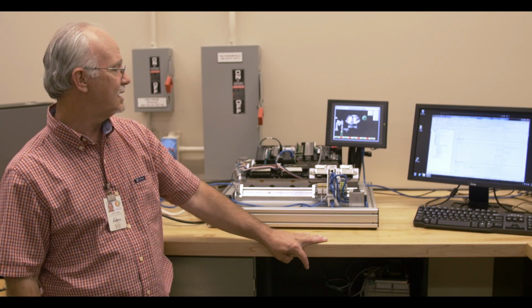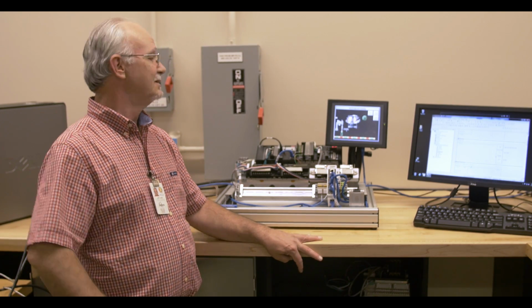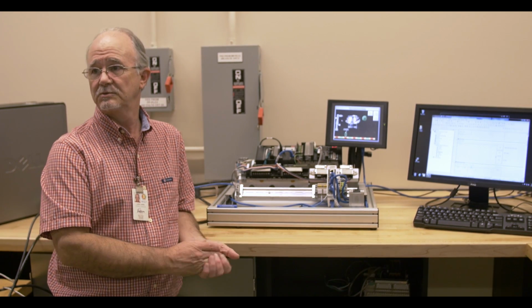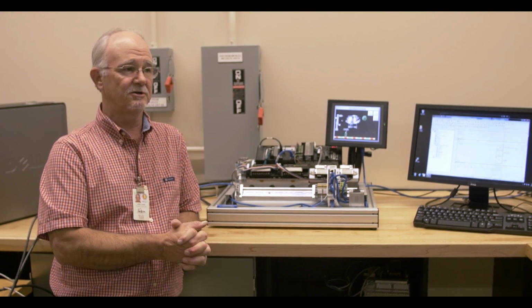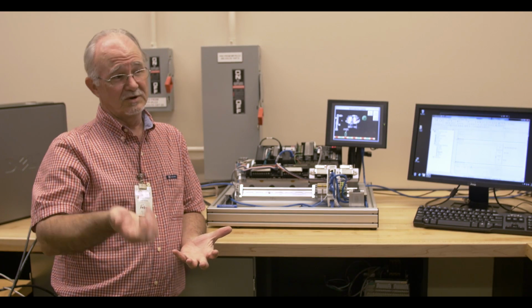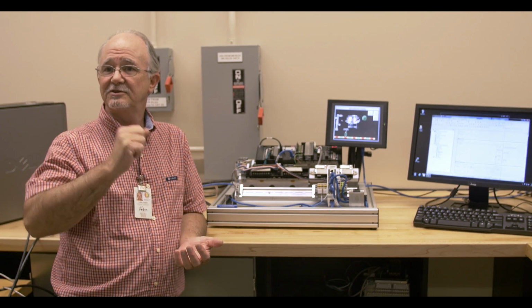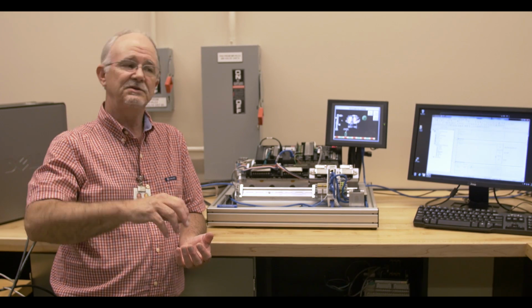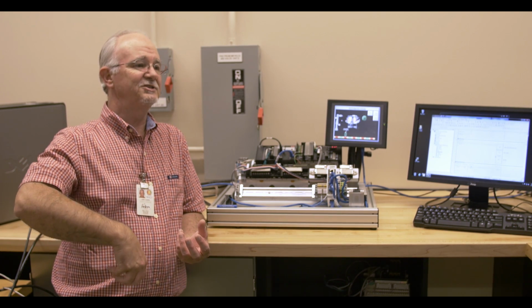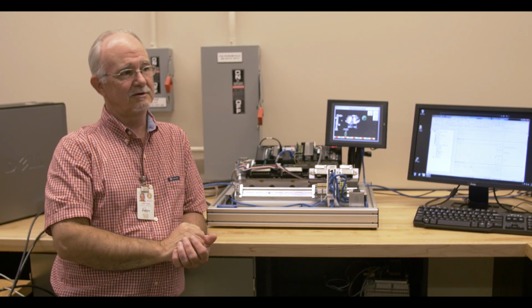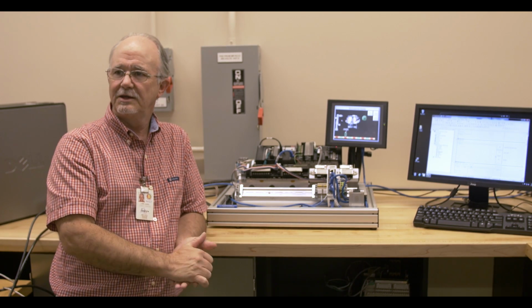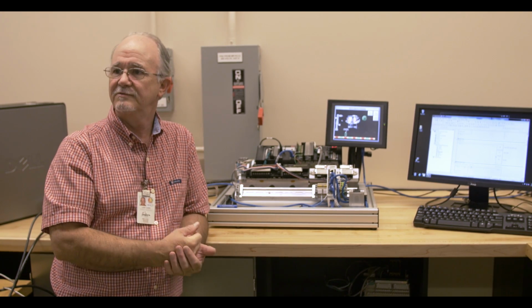Still relatively simple. The little robot picks a cap, goes down. We're using a torque sensor, so we're using an analog input to determine that we have the correct pressure on the cap. Once the torque level is achieved, it turns off the twist routine, turns off the place routine, so the robot goes back to the home position, clears out any memory bits that we've used, and it's ready for the next cycle.